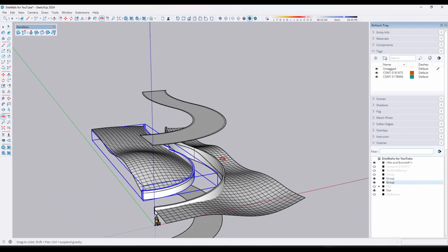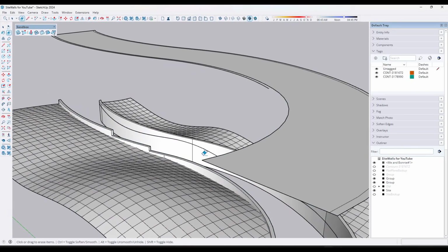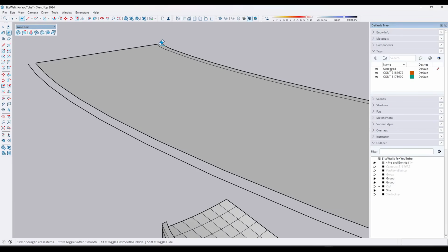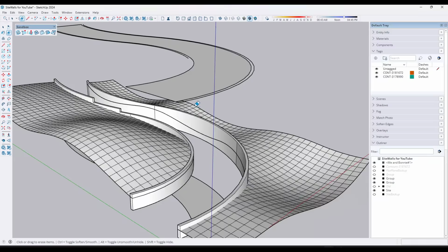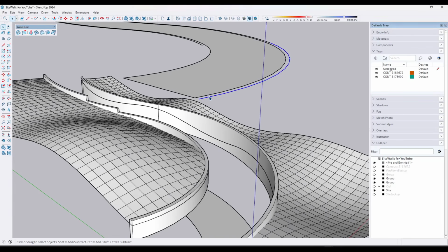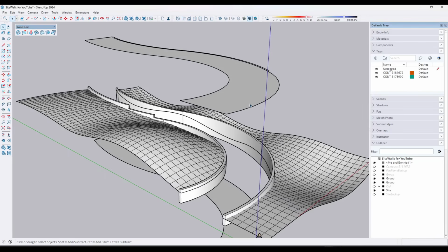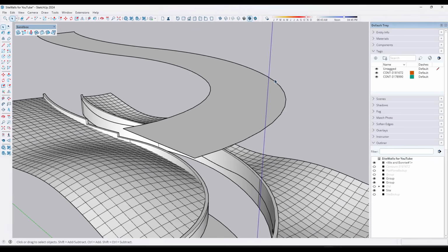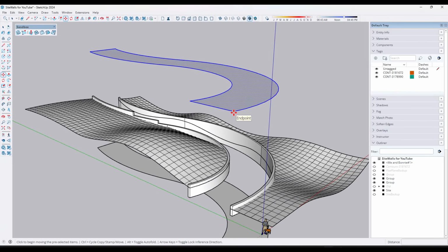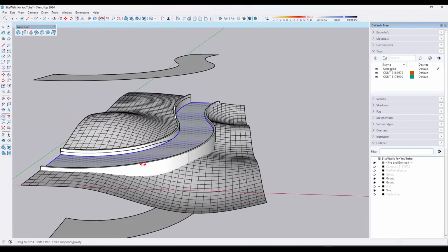So now what we want to do is bring our road in here. And what I don't particularly want to do in this situation is just have my road be flat. So if we wanted our road to be flat, we'd be pretty much done. So I'm going to get rid of these wall edges in here. We can just use the move tool in copy mode, copy this down. So not that big of a deal from that standpoint.